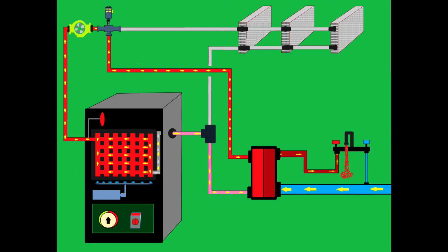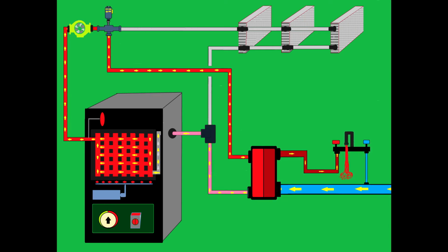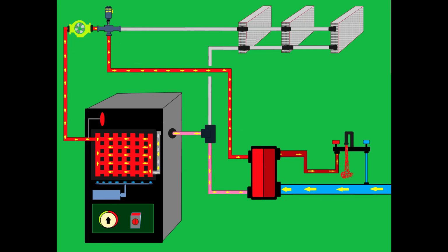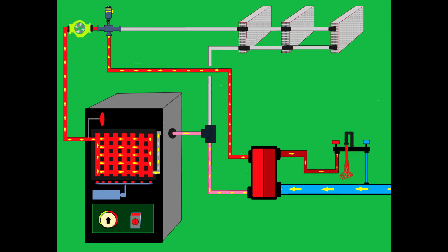What you have to understand is that anytime you open the domestic hot water in this situation, you'll have a diverter valve, like the 3-way valve you'll see there. There are many types of valve. I'll just give you an example because for me it's more important for you to understand the principle. And there are a lot of diverter valves and a lot of strategies to enable the boiler. You can have a hydraulic system which pushes micro switches.